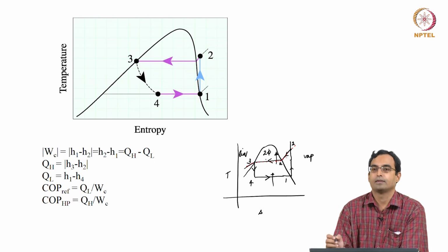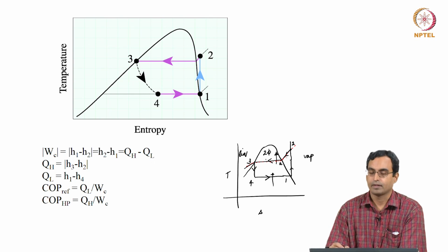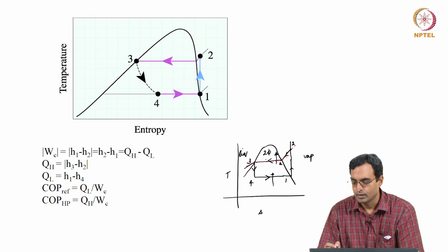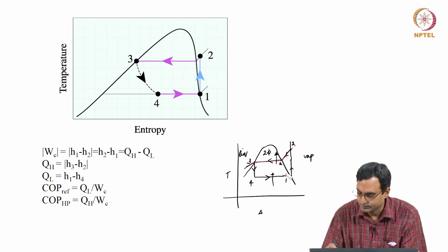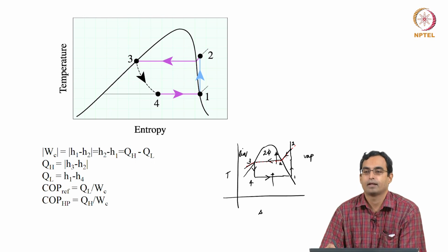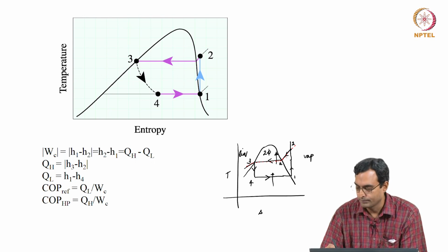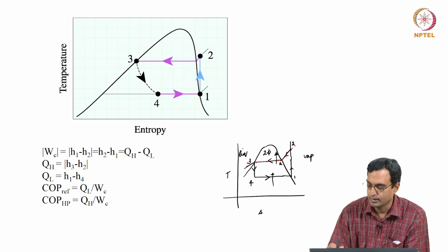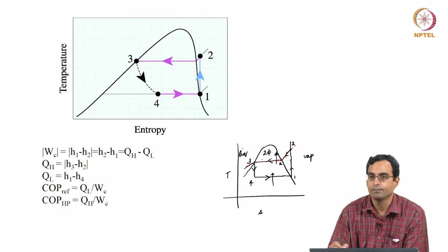The pressure is the same, but the temperature is different at different points in this region. So we are now left with this cycle, which starts at saturated vapor, dry saturated vapor at point 1. We are compressing to some temperature T2, the pressure at 2, A and 3 are the same.